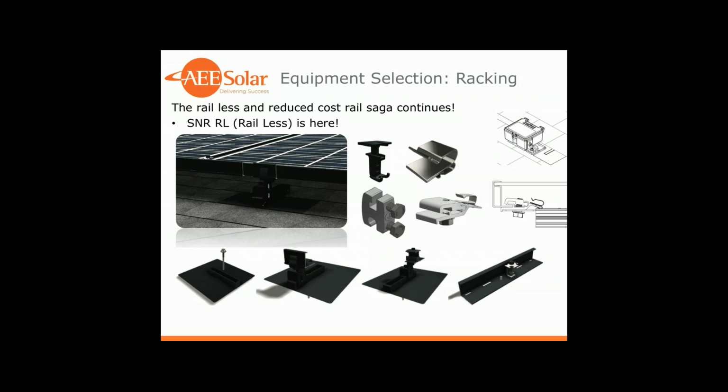And basically what I keep on hearing and seeing myself is that they typically install a little bit quicker than your standard rail systems, and in the majority of cases they actually cost less when you look at the total cost of the parts and pieces. There's generally a bit less aluminum used, so hopefully it really should cost less. And one thing that I've seen personally as well, due to the nature of the way that they link together and have the clamps and attachments in interesting places, is they typically allow for some more flexibility in terms of installation and module layout.